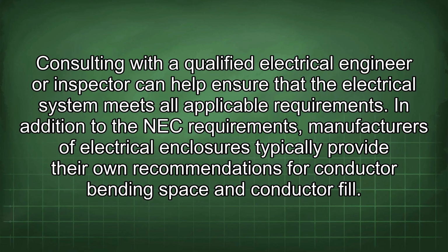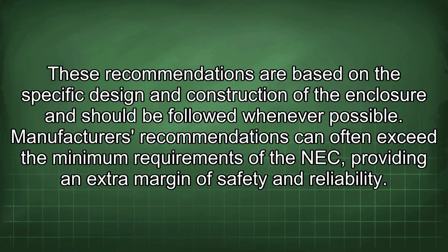In addition to the NEC requirements, manufacturers of electrical enclosures typically provide their own recommendations for conductor bending space and conductor fill. These recommendations are based on the specific design and construction of the enclosure and should be followed whenever possible. Manufacturers' recommendations can often exceed the minimum requirements of the NEC, providing an extra margin of safety and reliability.